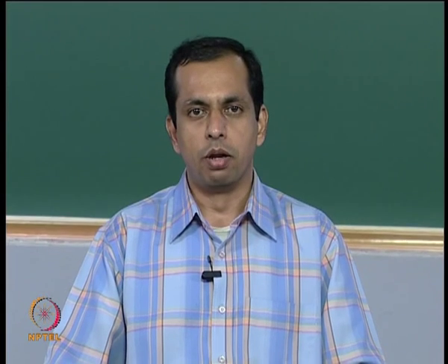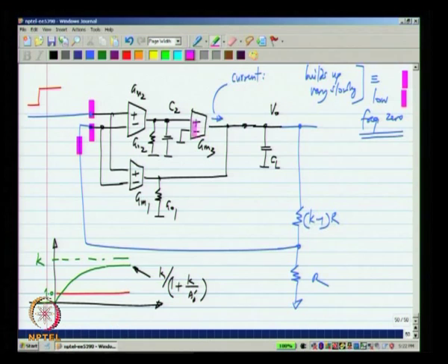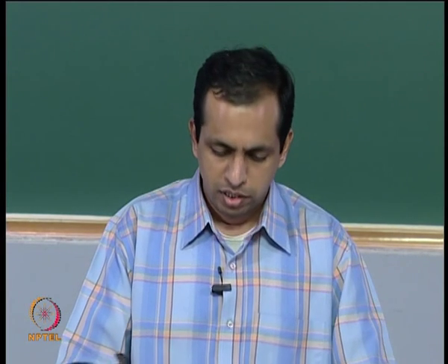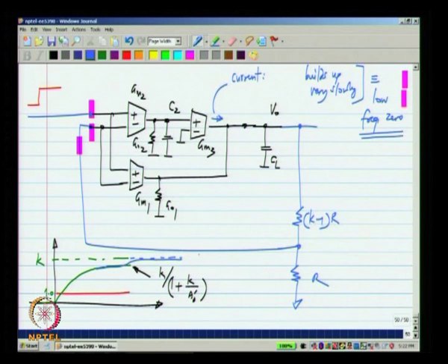Now, after a long time, the current output of the transconductance GM3 starts to build up significantly. So, what happens is after that, after a long time, this builds up and comes closer. So, although the DC gain of the op amp is high, it takes a long time to reach the low steady state error implied by the high DC gain.